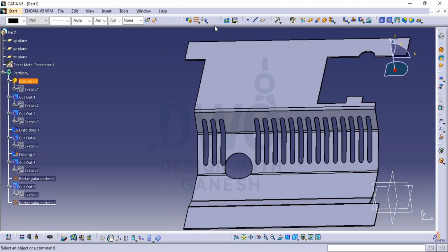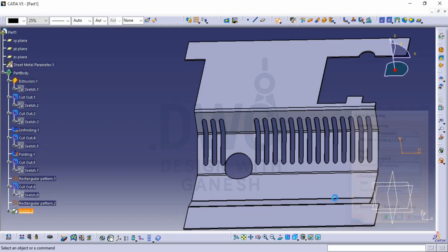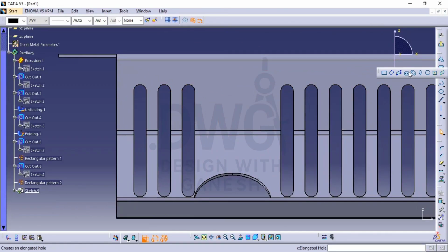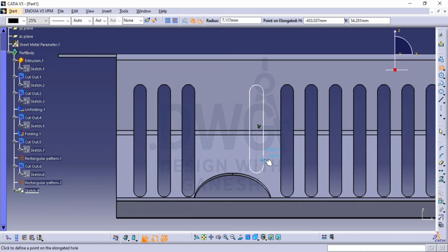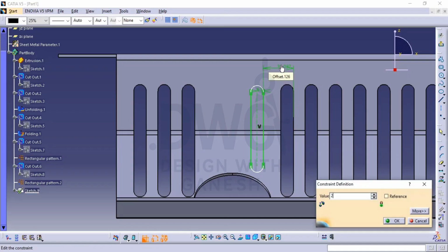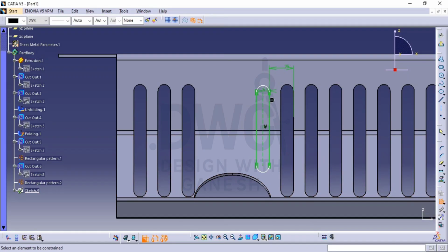So for that, click on the position sketch, select this plane, click on OK. Let's make 3 slots like this. This dimension is about same 6.5, enter, and from this line to this line, so it is about 25, and from this to this end point, which is 36.5.